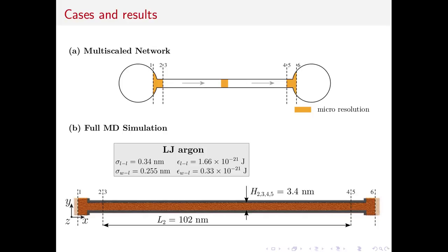And one thing you'll note is that the channel component is being modelled by just a single microelement, and we've deemed this acceptable because the channel height is constant along the channel length. So as long as the pressure variation is relatively linear, this should be a fine approximation. The boundaries are also highlighted by the dashed lines, and because it's a serial network, there are two boundaries for each component, because each component must have one inlet and one outlet.